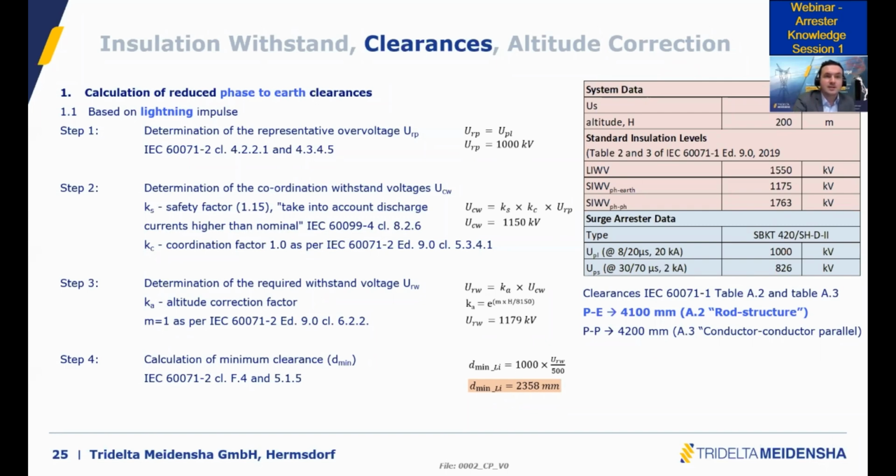So there is nonsense to close the UPL to the BIL level, because the possible over voltage will be close to BIL limit, right? I'm not sure if I understand exactly the question. So typically, if we take an example for a 245 kV system, a typical BIL for the system is 1,500 kV.